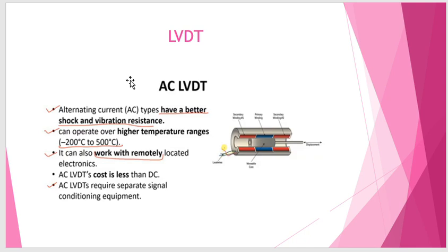It can also work with electronics located remotely, so we can use it with an outdoor electronic circuit. However, this LVDT tends to be cheaper and it requires an external circuit for signal conditioning. If I need to connect an output here, I have to hook up this lead wire to a signal conditioner.